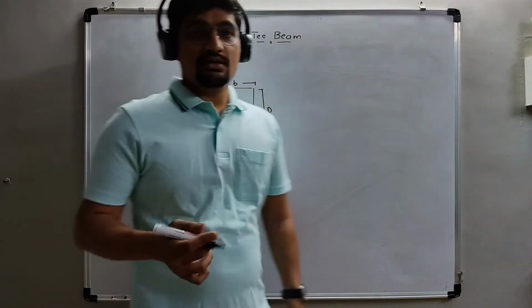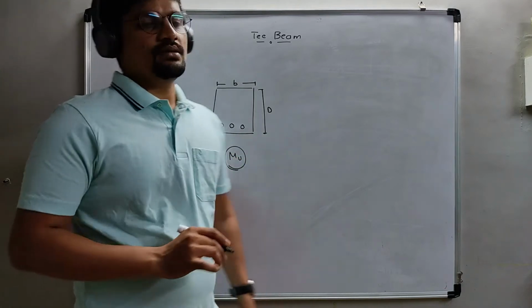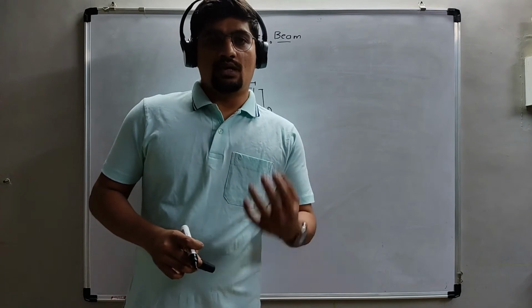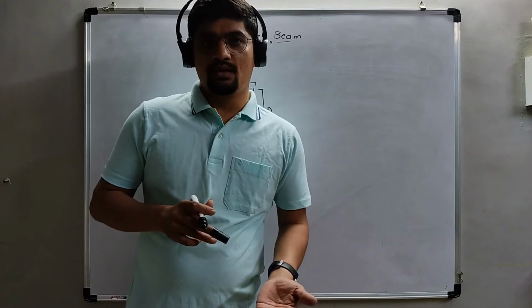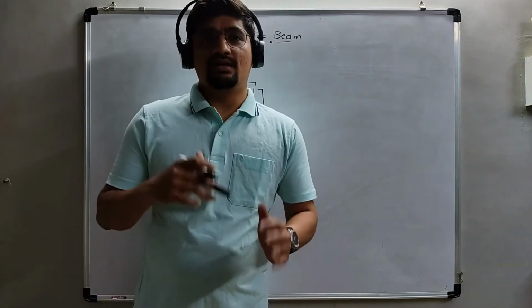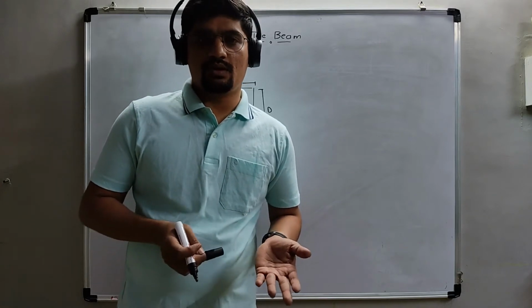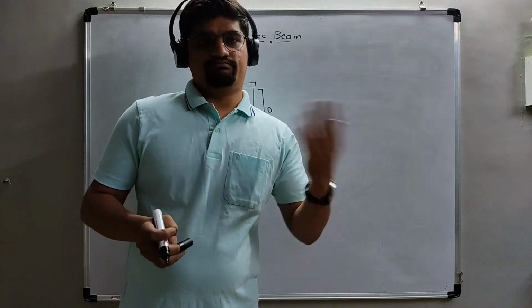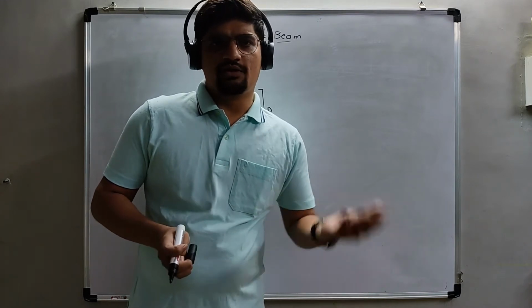But after doing the design and calculating the moment value, the result was that in some sections the required moment was not satisfied by the provided moment. As an example, the required moment is 107, and the provided moment comes to somehow 90 kilonewton meter.